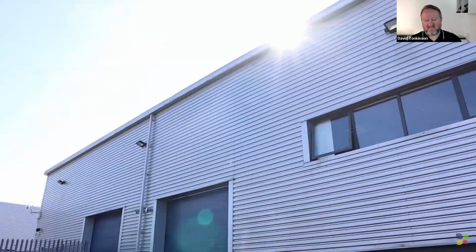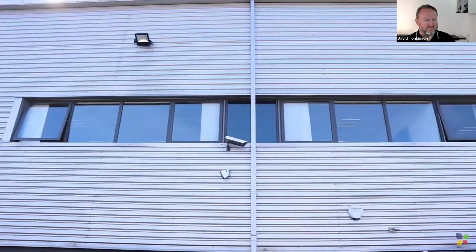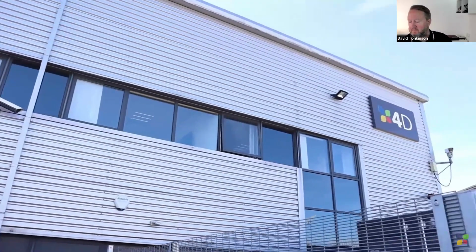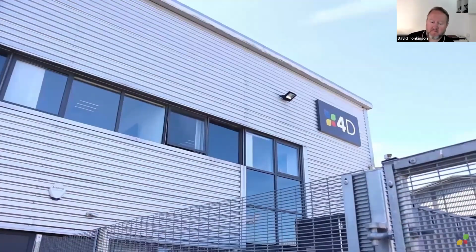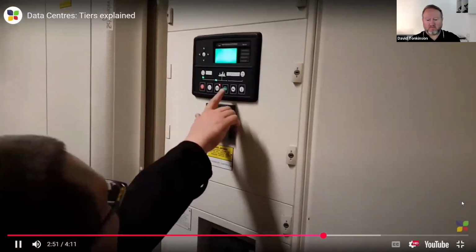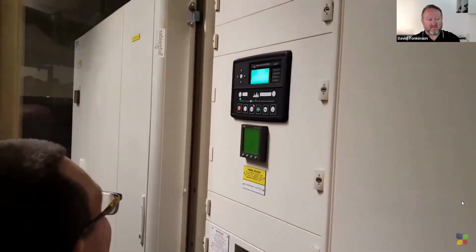What you should really do is go and do your own due diligence. So go visit the facility and meet the data center team that are running it. Find out what kind of planned preventative maintenance they do, find out what testing they've got in place and what kind of monitoring they're doing. If they're doing things like full building blackout tests where a mains failure is simulated, that's really good for ensuring the generators are run properly and the UPSs are working effectively. Having a well-run Tier 3 data center will generally give you much better uptime than a poorly maintained and poorly run Tier 4 data center.